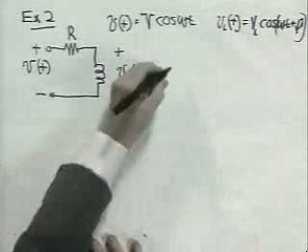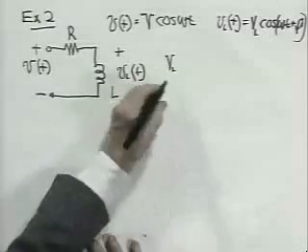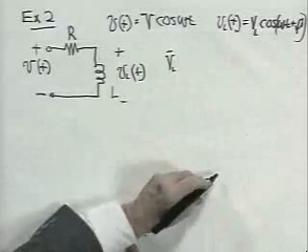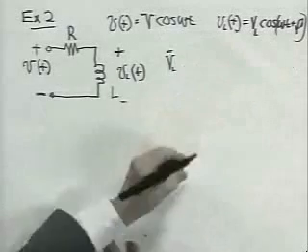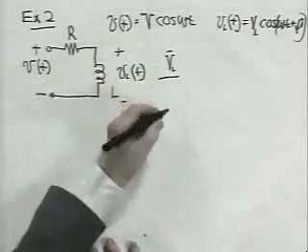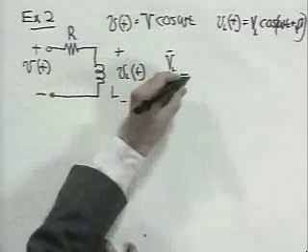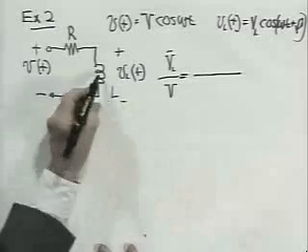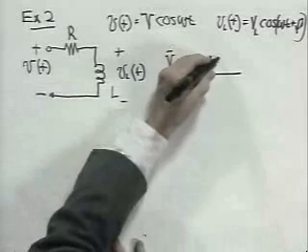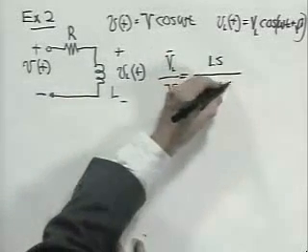The ratio V sub L is now a complex number because it embodies both the magnitude V sub L and the angle phi. The complex amplitude associated with the voltage V sub L divided by the complex amplitude, which in this case is just real, V, of the input, is, thinking in voltage division terms and recognizing that the impedance of the inductor is Ls, just Ls divided by R plus Ls.